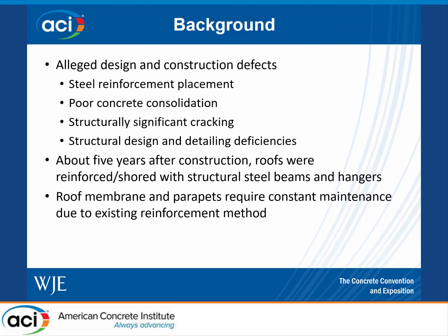Shortly after construction was completed, there were alleged design and construction issues related to rebar placement, concrete consolidation, cracking, and some structural design deficiencies. About 5 years after the construction, the roofs were reinforced or shored with structural steel beams and hangers installed on the exterior of the building. The roof membrane and parapets required a lot of maintenance over the years due to the existing reinforcement method.